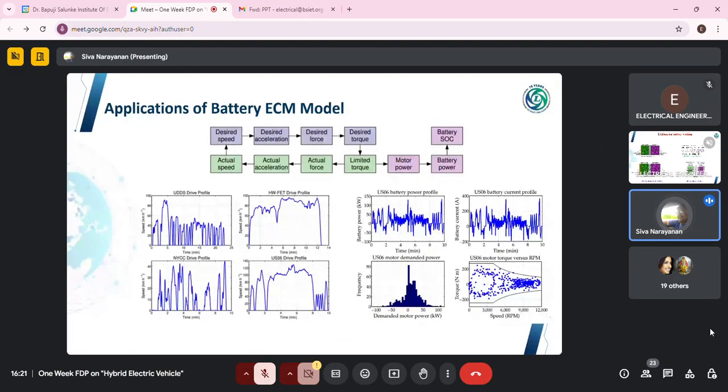Here you can see that as the speed increases, the torque also increases, and you see both the positive torque and the negative torque, which are used for positive acceleration and negative acceleration, where you can see plus 200 and minus 200. The small number of dots represent the points where, for the entire driving cycle, our speed torque characteristics get intersected. One big black line goes above 200 and below minus 200, both on the top and the bottom. If all these blue dots are within this range, then it ensures that our design is correct.